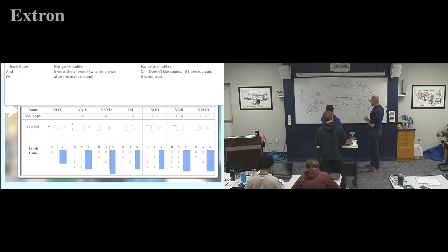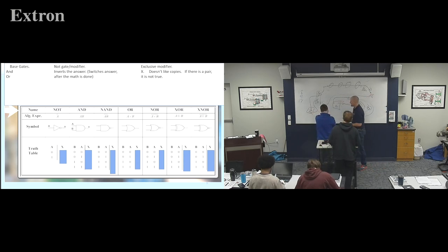I'm sorry, I think we just said two opposite things. So I'd be 0 here because it's the same wire. From here it would be 12, because this point is my plus 12, right? We could say plus 12. This is still my, I'm gonna call it 0. If I go all the way to plus 12 here, I gotta make that one 0. So what I'm getting hung up on, I think that makes sense. Measure there to there, it's 0 volts, because it's a wire.